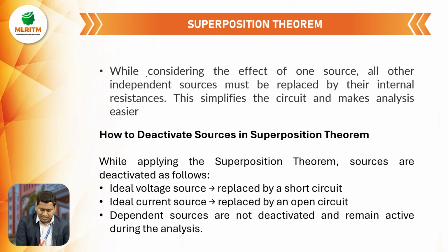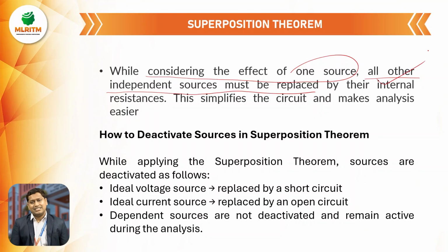While considering the effect of one source, all other independent sources must be replaced by internal resistance. This simplifies the circuit and makes analysis easier.